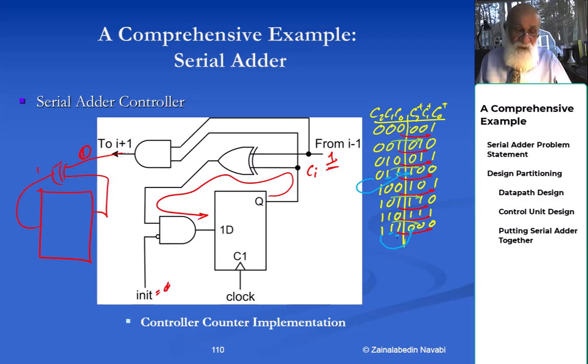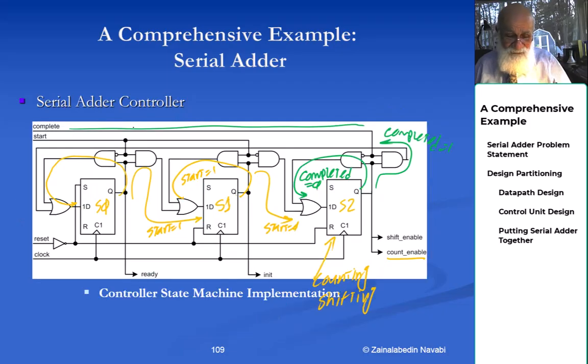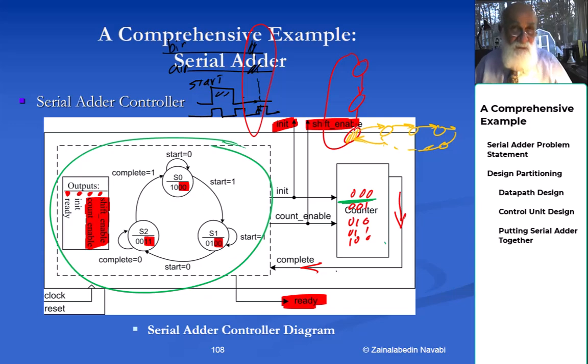And therefore putting 3 of these next to each other gives you a 3-bit counter. It gives you a carry in that you have to set to 1. It gives you an init signal that you reset to 0. Also, the very last output from the third bit, the AND gate, is the carry out, which you're treating as completed. Okay, which is completed, that comes here.